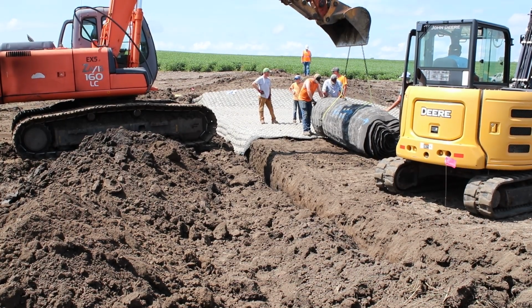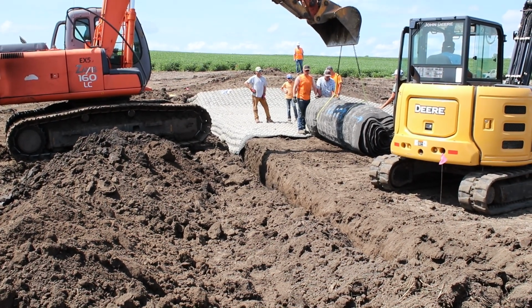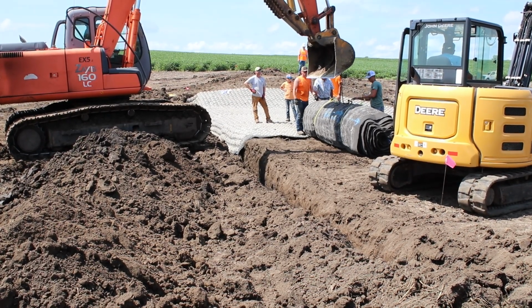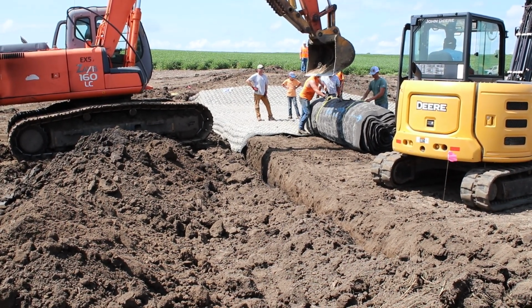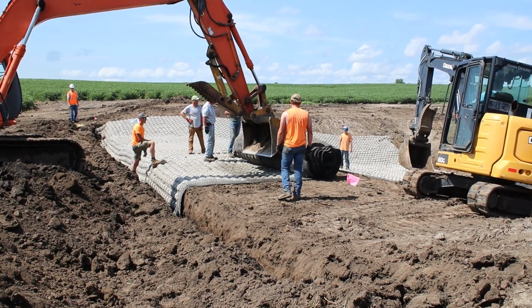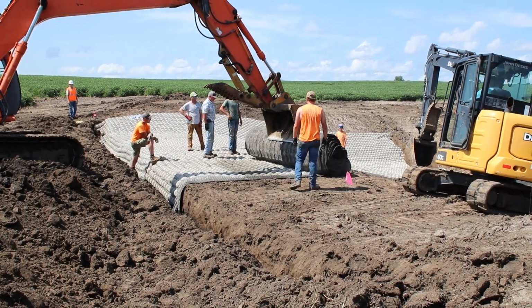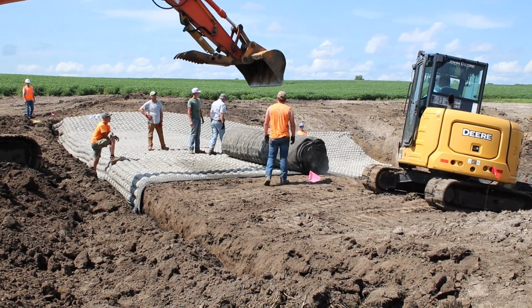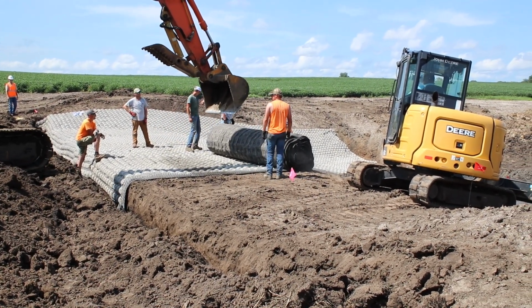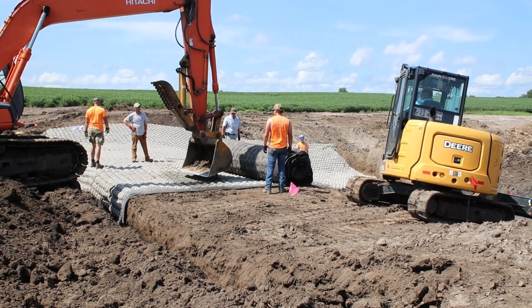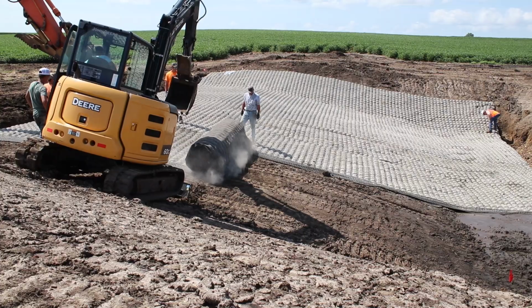As each roll was moved into position, the excavator made sure the roll was placed in the right direction so it would unroll down the slope and it would follow the desired line as they unrolled it. For this project, the rolls were unrolled from the top to the bottom of the slope. In some cases, the rolls are unrolled across the slope instead. The first roll on this project was placed at the far north side of the chute. Then they worked their way across the chute.